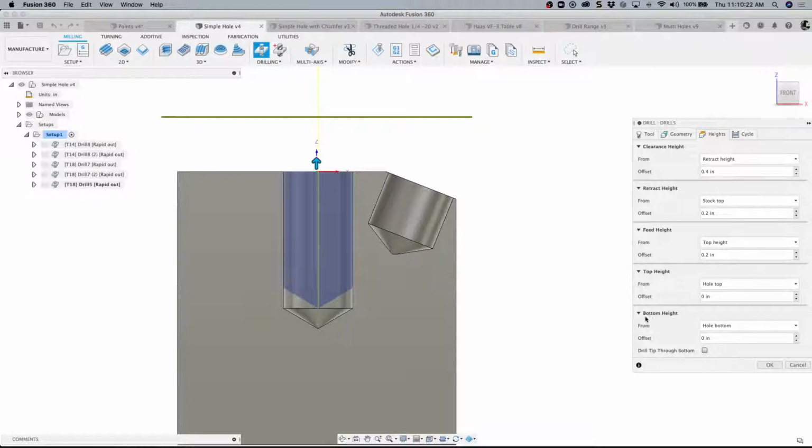So I generally start at the bottom, and it says the bottom height is the whole bottom. And the top height is the whole top. So this is useful if you're doing anything on your modeling, and if you change things up. And let's say I change my hole depth because I told it obey the whole bottom. This will automatically update, and I can dive into that and show you.